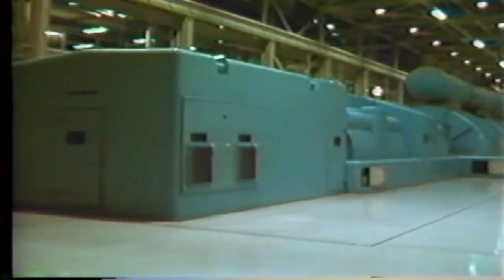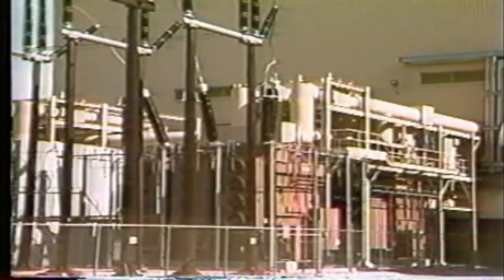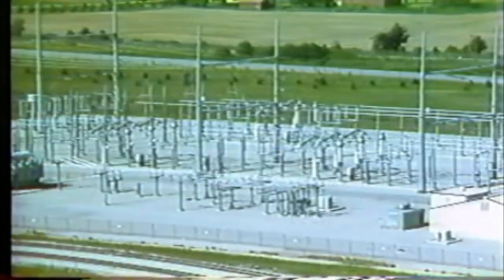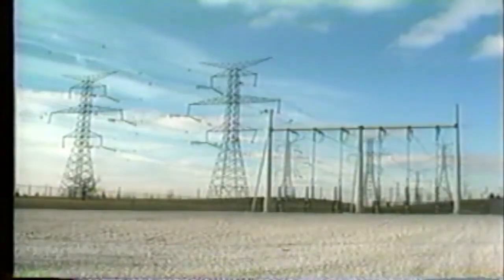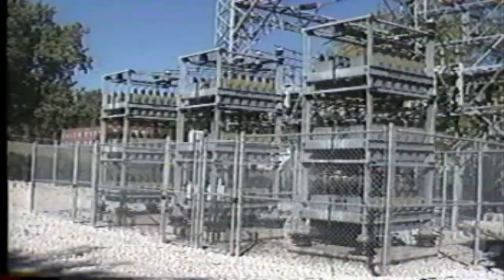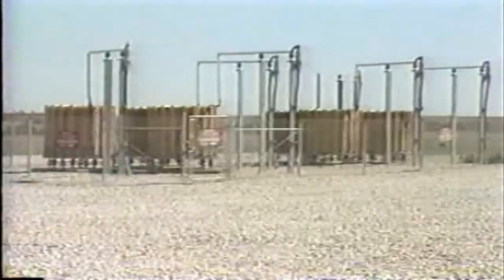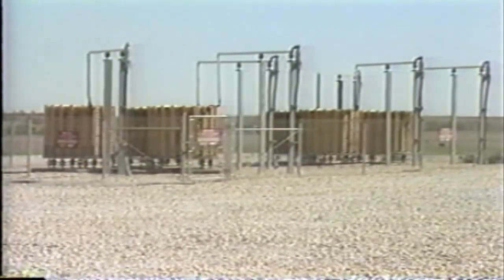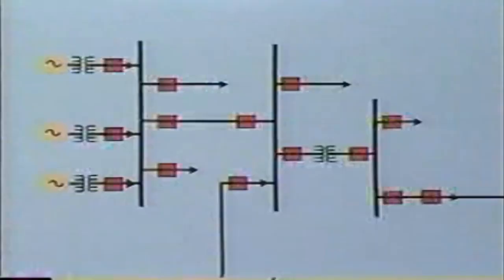In our typical power system, we have generators, including their step-up transformers, buses, transformers, transmission lines, sub-transmission lines, distribution lines, and utilization equipment such as motors and static loads. Also, on most systems, capacitor banks and reactor banks are installed. Now, all of this equipment needs to be protected, but the type of protection used is generally different for each area. So it is convenient to apply the protection to distinct zones.